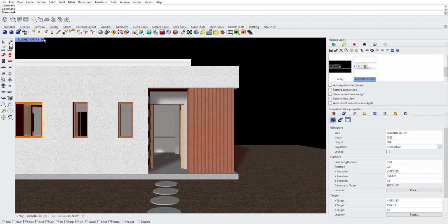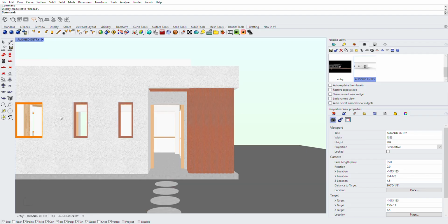The way that we do this, I'm going to go back to that shaded. You click on the viewport bar and go down to display options. Once you have display options on in our shaded view, we want to make sure that if we scroll down here, I unclick light, and for my lighting method, I choose no lighting.